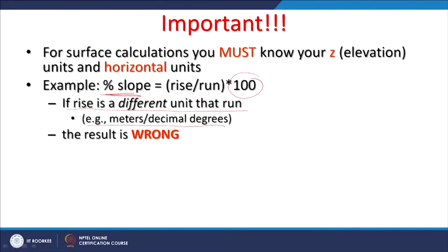And so, while doing this demonstration on computer of slope calculation, I will show you what difference it will bring if you do not take care about the Z factor. That means the elevation and horizontal units must be of the same type, in meters, and if they are not, then the Z factor cannot be 1.